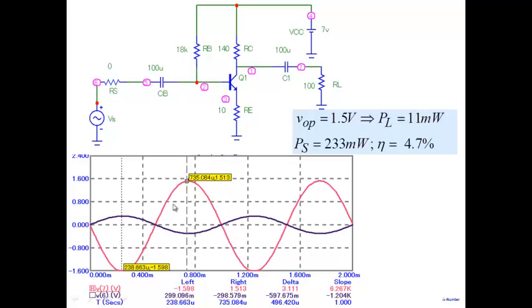In fact, what had happened was one had designed this amplifier without thinking about an RE drop here, and that's why we can't reach 2 volt here. We could reach only 1.5 here. So you can go back and redesign the amplifier, not for 2 volt. You designed it for 2 volt and the swing became 1.5.